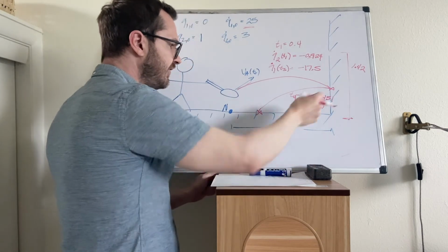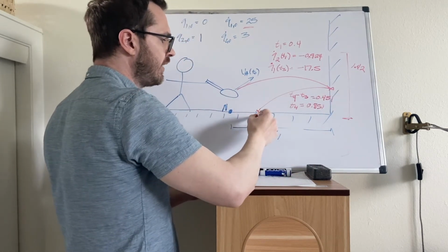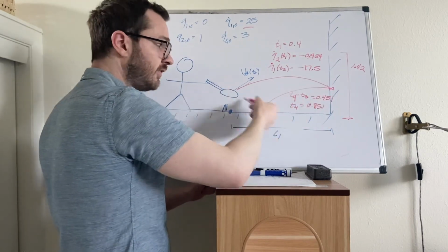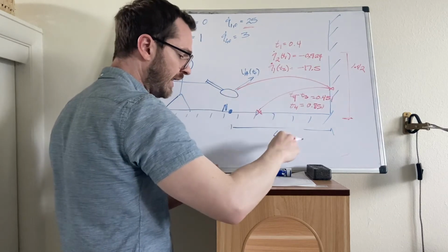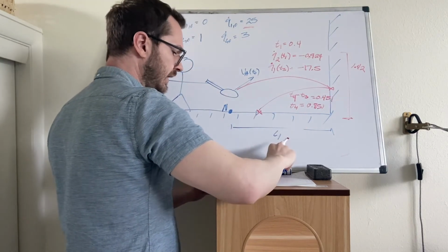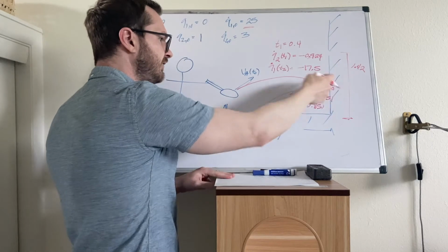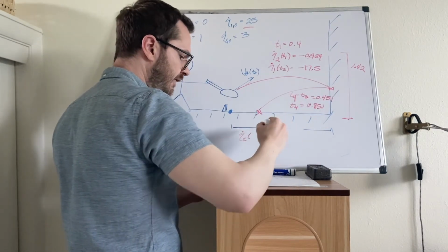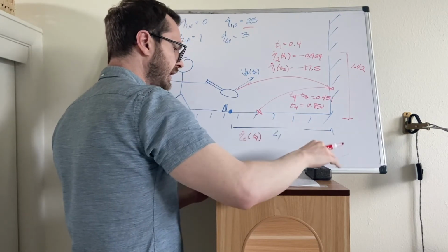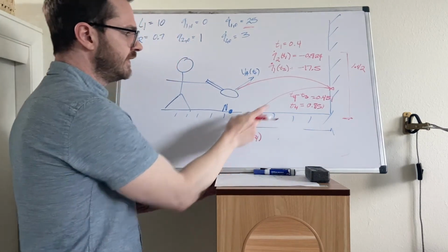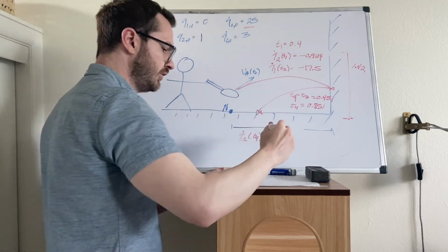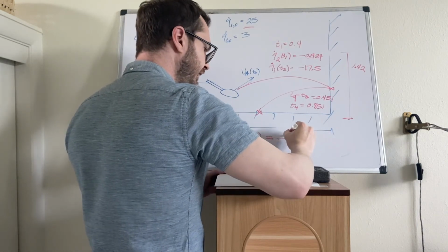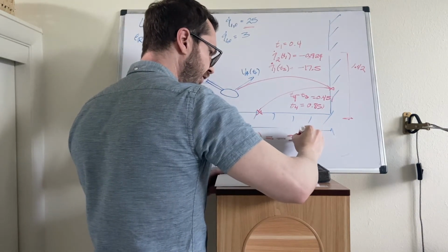What do we need to go into this second impact? Well, we already have the velocity in the x direction. It was negative 17.5, and without friction, it remains constant in this bounce, so we don't have to recalculate that. We do need to know the velocity going in, so we need Q2 dot at time 4. And again, you can use those ballistic equations. If you know the time, you put it into the ballistic equation, you get the speed, and the speed going into the impact is negative 5.35.